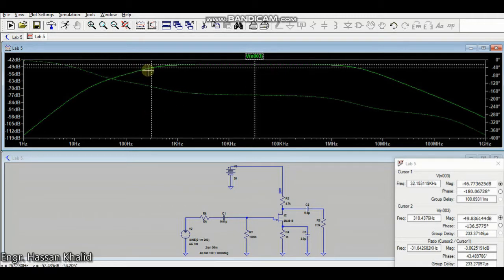And similarly, the high value of the frequency is exactly at 3 decibel units from the high cutoff frequency side. That means this region is the low frequency range, and this region on the right side is the high frequency range. So we can easily move this cursor toward the same axis that matches with cursor 1. So now note down these values.